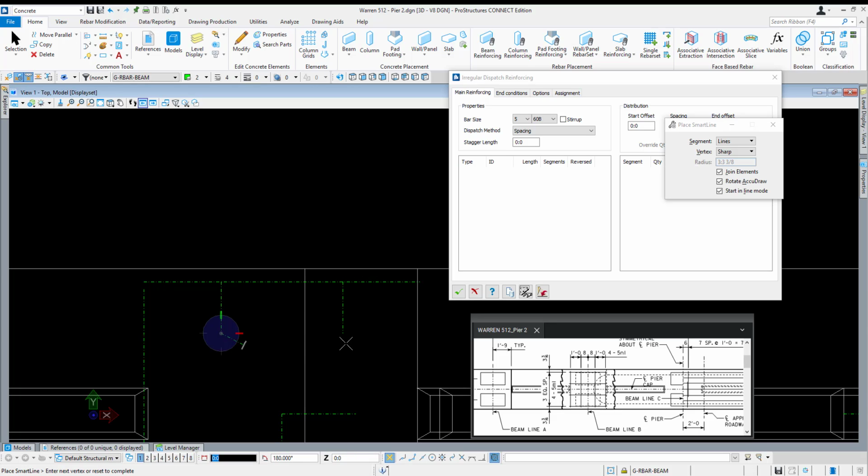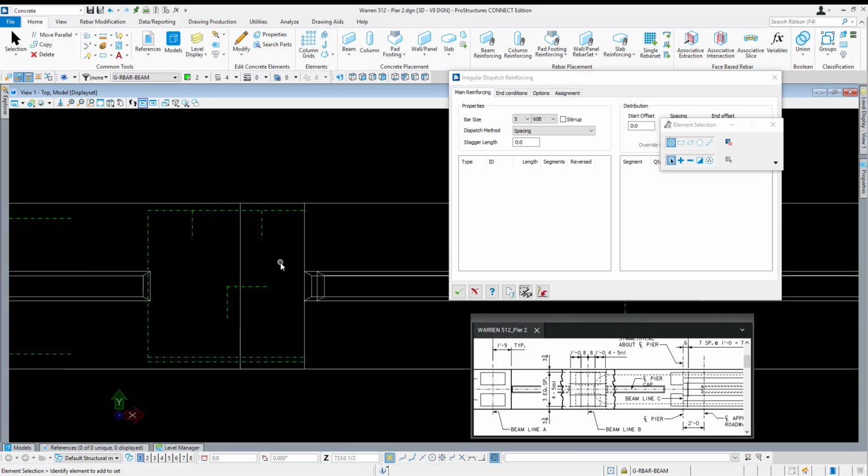And just to double check, do we have 1'7" in there, roughly? I could shift the beginning and end of these bars in a hair more if I wanted. Totally up to you. Again, I'm just using that 3'7" value that I figured a minute ago. It's probably 3'6" in the end. So we're going to copy this over to the other side so we can use the vertex method.